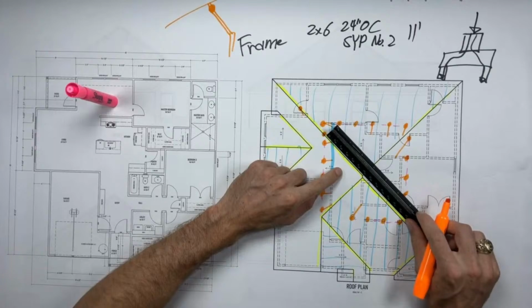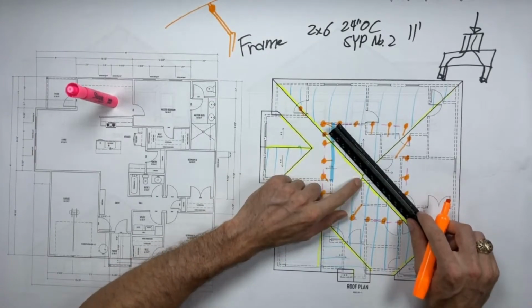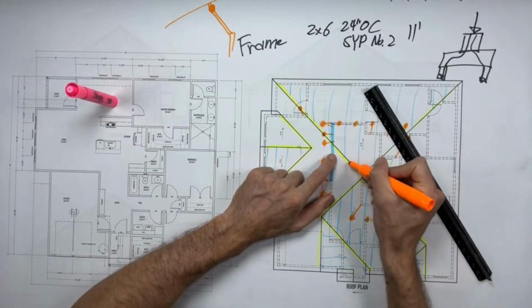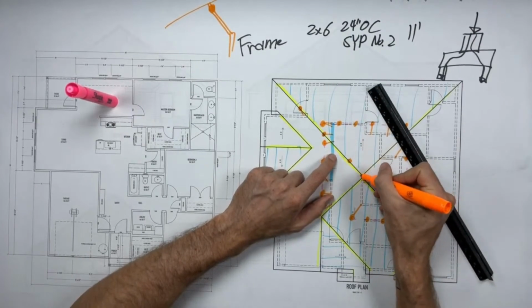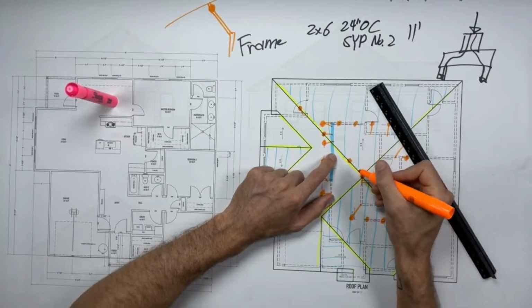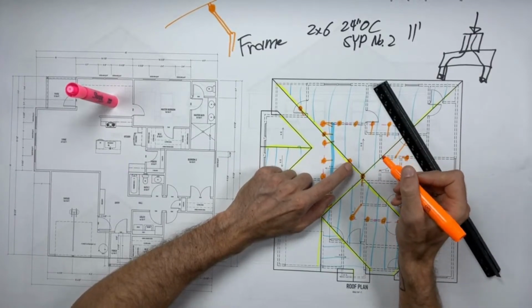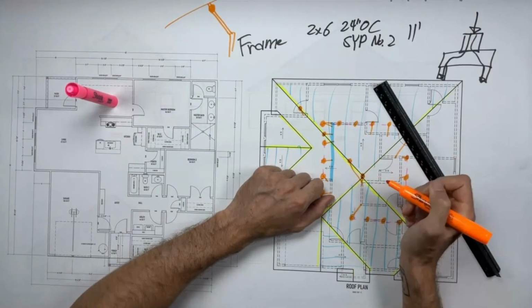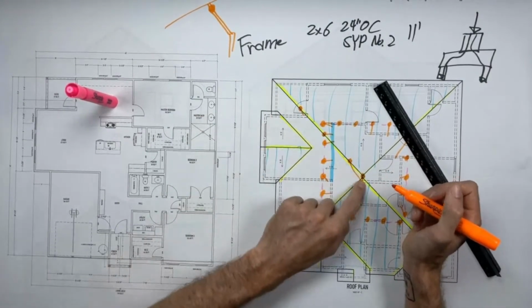So what I could do, yeah, that's 10 feet. Even the beam all the way to here is 10 feet. So I need another one. So what I'm going to do is go to 8 feet. I know it's out here somewhere. And you're going to brace this whole chunk in the center down to the wall. But I've got lots of room. I got lots of height up here. So I'll probably also brace this down to the wall as well. All right, so this guy's good.